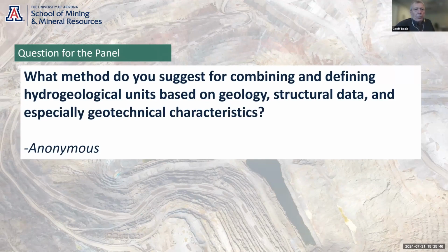And structural orientation and joint orientation is really important, because typically the joints open more when they're parallel to the slope. So where you have joints or structures parallel to the slope, they open up. And if they open up, they potentially lend themselves to water ingress. If they're perpendicular to the slope, if they're in and out of the wall, they tend to deform and open up less. And so you get less influence on the water.